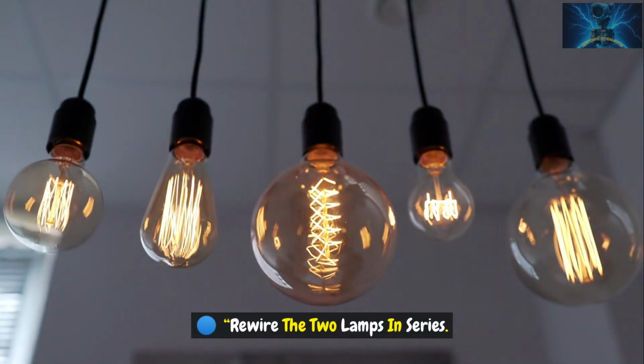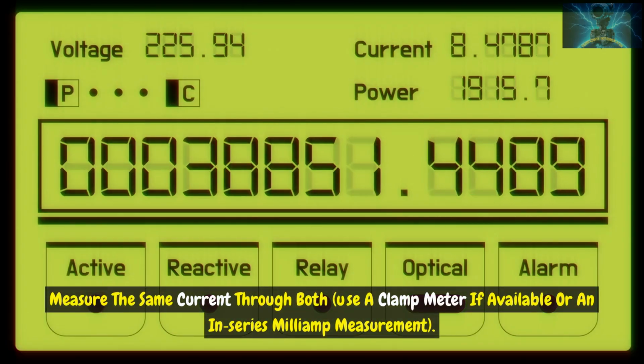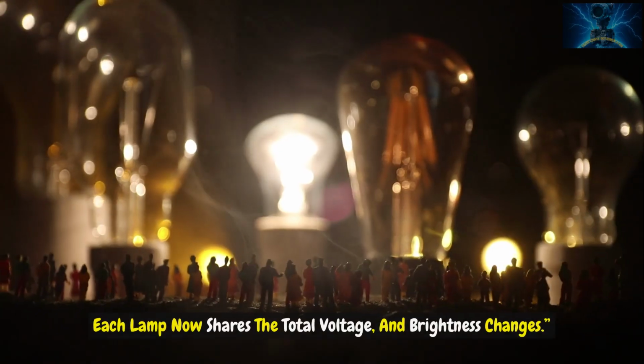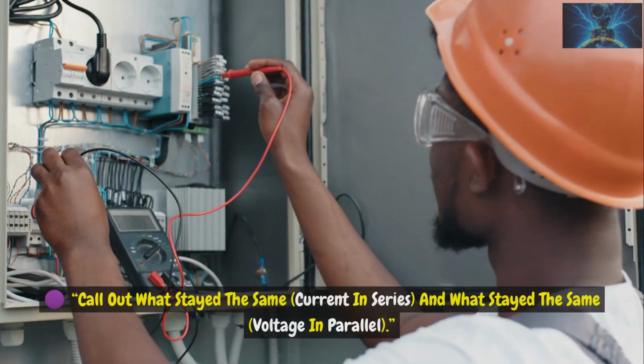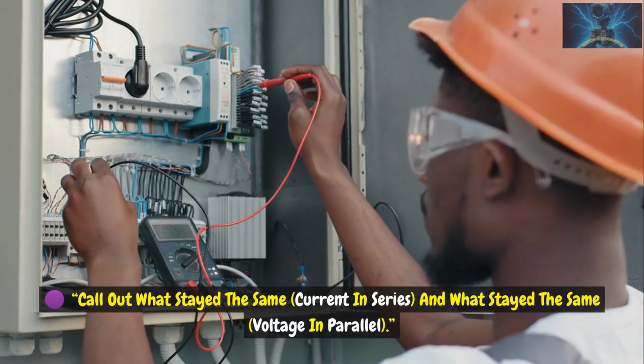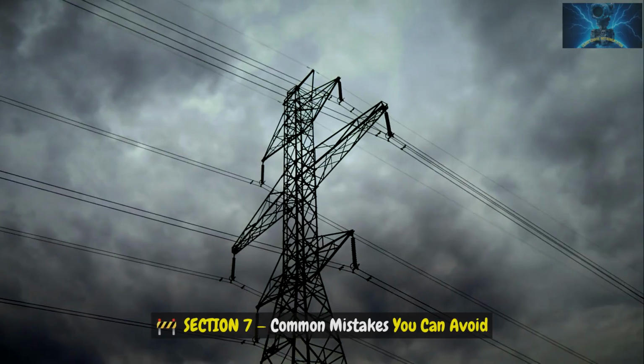Rewire the 2 lamps in series. Measure the same current through both. Use a clamp meter if available, or an in-series milliamp measurement. Each lamp now shares the total voltage, and brightness changes. Call out what stayed the same: current in series, and voltage in parallel.